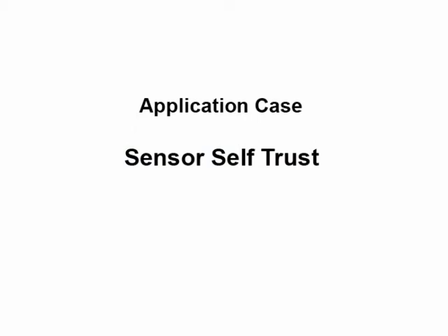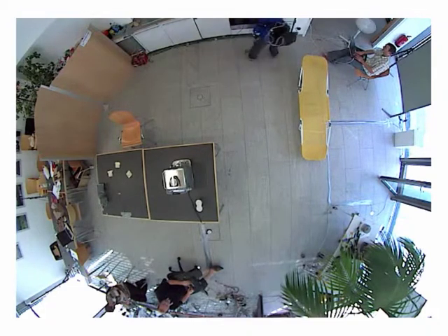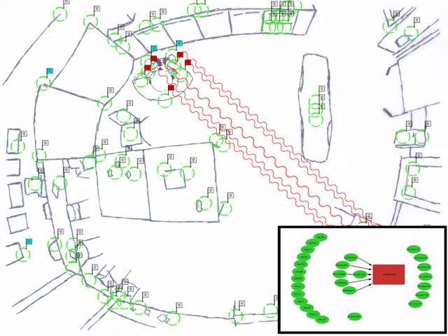As sensors are sensitive to changes in their position, the Opportunity framework is capable of detecting faulty data being delivered by a sensor that changed its position, got rotated, or is malfunctioning. Each sensor is aware of how plausible the data it delivers is. This reliability measurement, called trust indicator, indicates the self-awareness capabilities of the sensor, describing how plausible and trustworthy the data it delivers is, as a value between 0 and 1.